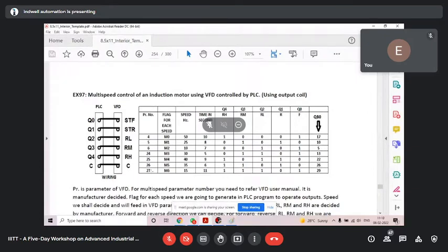Now you see. After feeding the multiple speed frequencies, and you do all the settings, or if you have connected with PLC, you will do the program and all. You will press the start button, and you can see you have set the time also. That speed number 1, 10 seconds, then next 8 seconds, 7, 5, 9, 6, 11, whatever you have fed.